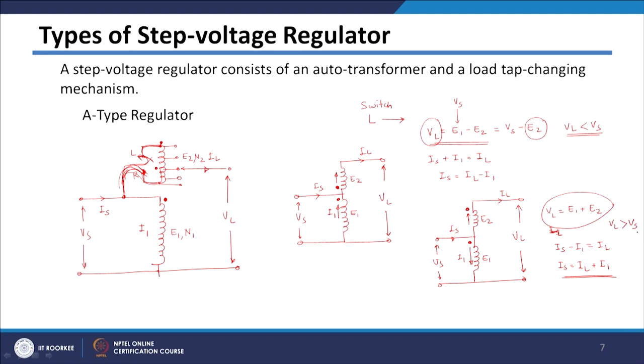So, you are raising the voltage from the source voltage, that is why I am calling this terminal the raise, R terminal. And here, when the switch is on this side, we are actually lowering the voltage, which you have seen here when VL is becoming less than Vs. So, that is why I call this switch position L. This particular condition which I have shown here is for switch position R.